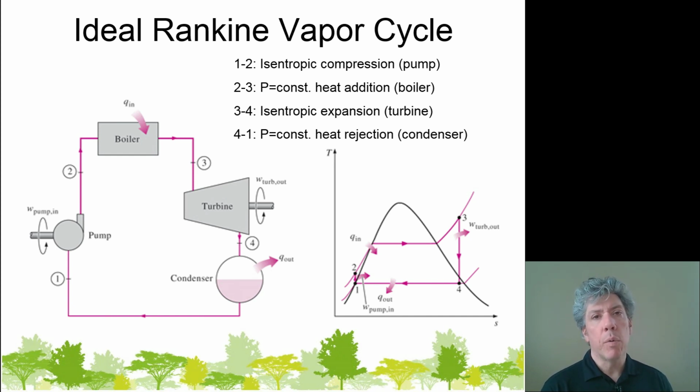So the boiler will have to take subcooled liquid water, increase its temperature to the point where it becomes a saturated liquid, boil off all of that liquid by continuing to add thermal energy to it. And even though we get to the point where all the liquid has boiled off, we want to add even more heat to it by burning a fuel, because now it would all be steam. We want to move that steam into the superheated region.